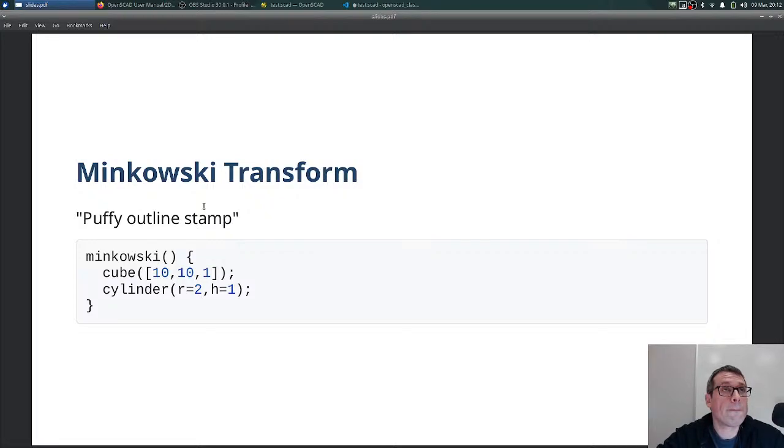Rounding the edges like that is the hardest thing to do in TinkerCAD. Oh, is it? Yeah, somebody just mentioned that in Tinkercad they've had some challenges rounding the edges. So yeah, this makes it pretty easy. It can get a little tricky when you're dealing with precise widths because you have to account for the shape that's actually being applied as the second argument. You have to take that into consideration. But it's nice. It takes two objects generally.